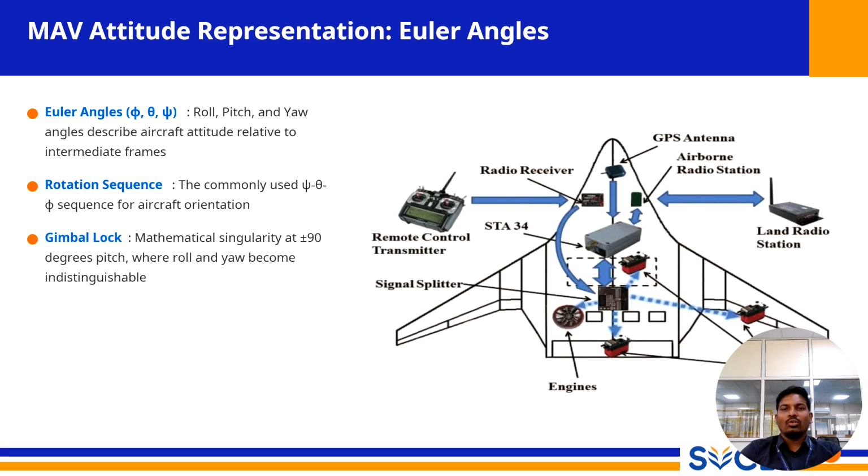It is very important to note that the order in which you apply these three rotations matters. If you roll the drone first and then pitch it, you will end up in a different orientation than if you had pitched it first and then rolled it.